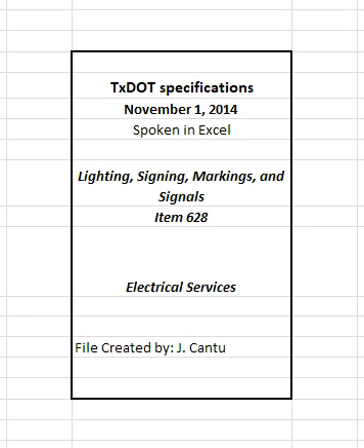3.3 Removal. Coordinate removal with the appropriate utility company before beginning work. Before the removal of the electrical service, disconnect and isolate any existing electrical service equipment in accordance with the utility company's requirements. Remove existing electrical service support a minimum of 2 feet below finish grade unless otherwise shown on the plans. Repair the remaining hole by backfilling with material equal in composition and density to the surrounding area. Replace any surfacing such as asphalt pavement or concrete riprap with like material to equivalent condition.